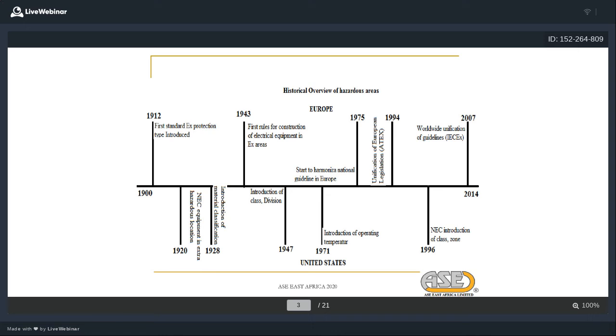So the miners were using the so-called Davy lamp. This lamp consisted of a lamp with the flame enclosed inside a mesh screen. The screen acted as the flame arrester. So when the air came in contact with this flame, it could not pass through the mesh, so that could support combustion.